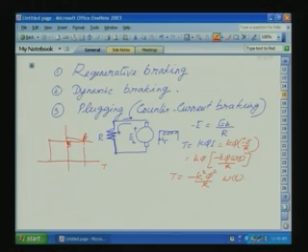Okay. Then from there it will slowly move along this direction and come to 0 here. This will move along this path and slowly come here to 0. So why? As the speed decreases, current will decrease, torque will reduce and slowly come to 0. When it comes to 0 here, the back EMF will also be 0, speed is also 0.